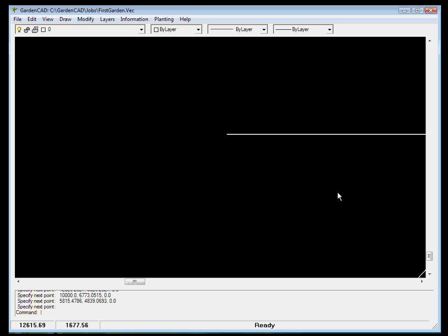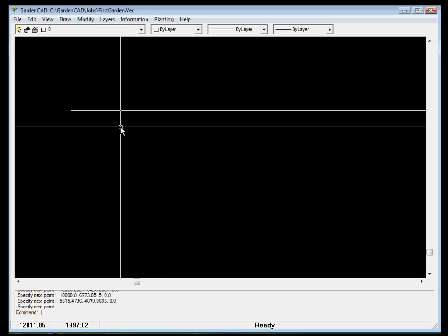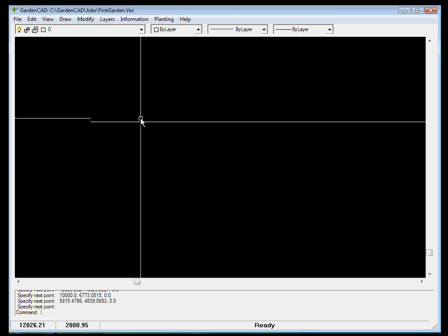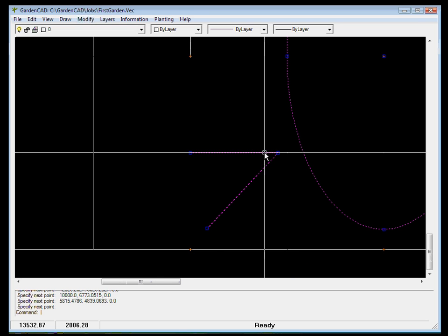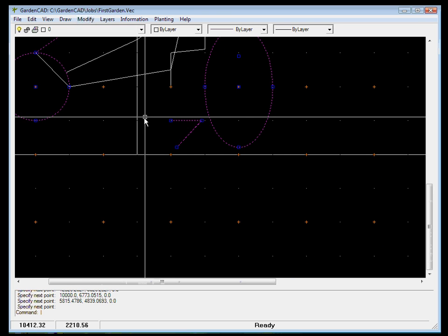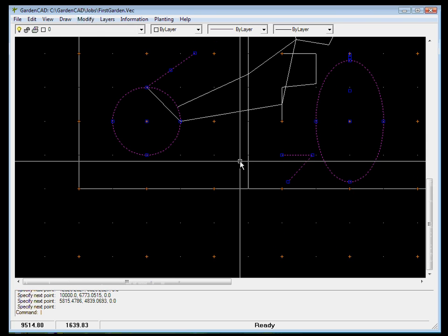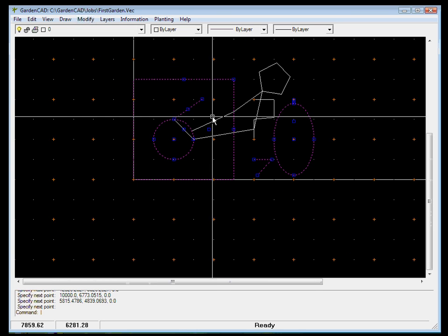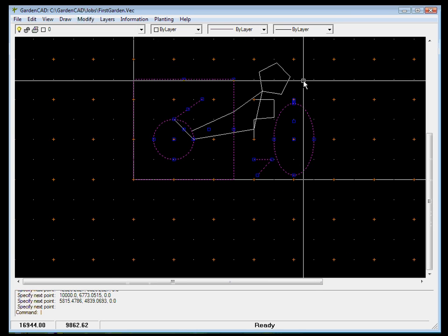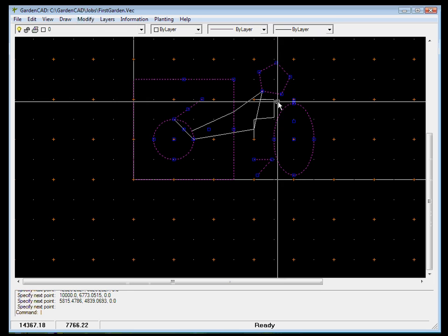Here's a multi-line. If I zoom right in, can you see it's 2 lines? So if I click on the multi-line and zoom out, I get an anchor point there, or a grip in that direction. A rectangle. I've drawn a rectangle here. Click on it. I have 4 grips on the rectangle. So here's a polygon. There should be one at each vertex of the polygon.